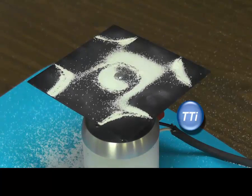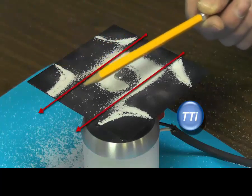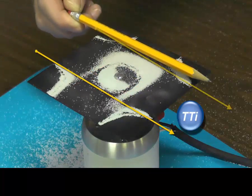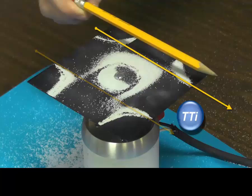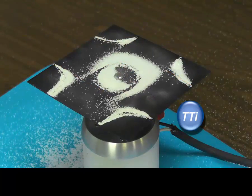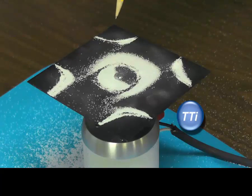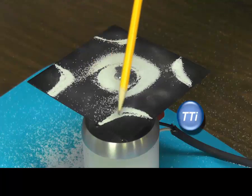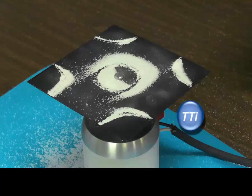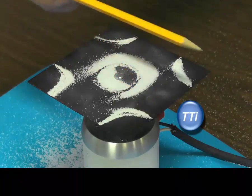What we've found now is we have multiple node lines. Two node lines going across here, and in the other direction, two node lines going across here and here. A little bit of curling in the corners. This is a classic mode for a plate where we see in phase, out of phase, in phase, in phase, out of phase, in phase, in phase, out of phase, in phase, all across the plate. A node line across here, a node line here, a node there, and a node there.